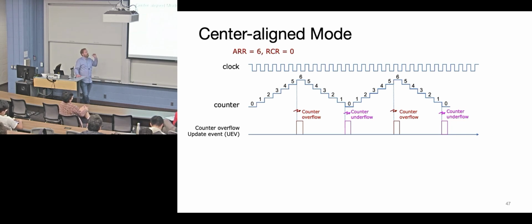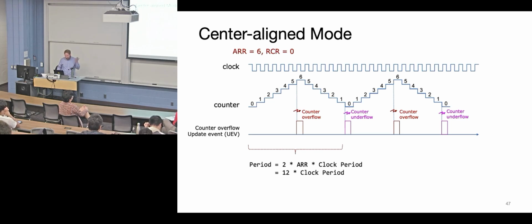So you might set up a timer that is just counting up, and then you could have multiple outputs of it with multiple reference signals. With one timer, you can set 4 or n different PWMs going off. And it doesn't have to be PWMs. You could also have interrupts or other timing events. Okay. So in this particular case, the clock cycle would be 12.